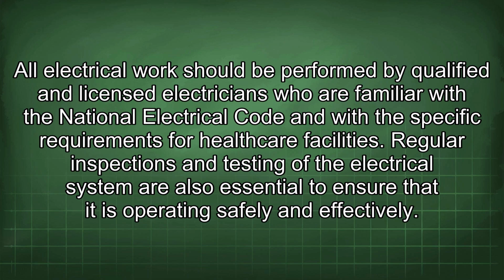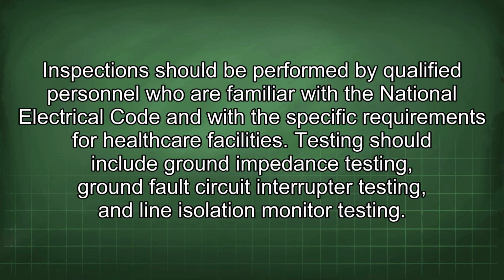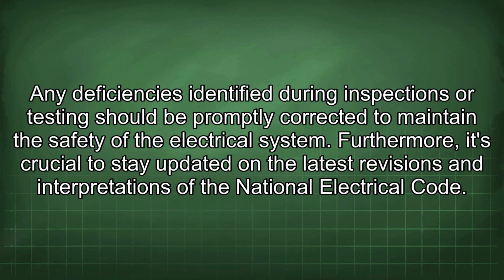Regular inspections and testing of the electrical system are also essential to ensure that it is operating safely and effectively. Inspections should be performed by qualified personnel who are familiar with the National Electrical Code and with the specific requirements for healthcare facilities. Testing should include ground impedance testing, ground fault circuit interrupter testing, and line isolation monitor testing. Any deficiencies identified during inspections or testing should be promptly corrected to maintain the safety of the electrical system.